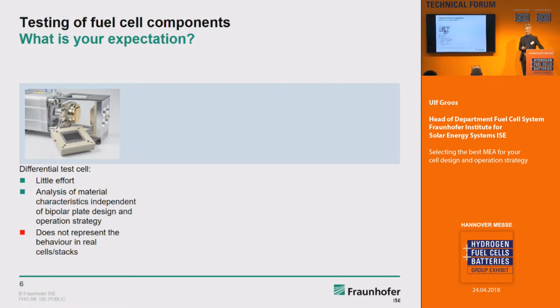Cells like these are developed to analyze the material characteristics without any major influence of the bipolar plate design, of the flow field design, and no influence of the real operation strategy.